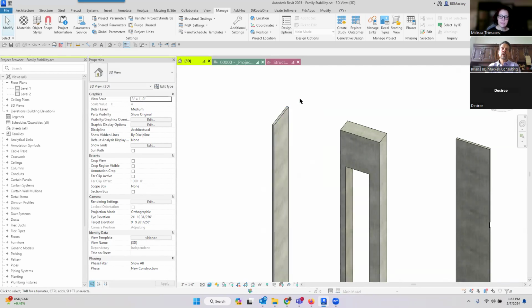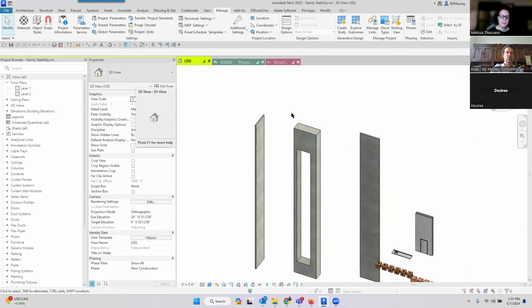So you can transfer, but again, you'd have to copy that one wall type out if you only wanted the one wall to a different project that doesn't have it. Blank file, and then transfer project standards over. But if you're talking walls and materials and all of it, it doesn't do it. And thank you to whoever typed in the JO tools. Yeah, they do have those, and I knew somebody had a tool, I just wasn't sure which one. There are tools out that say, I want to transfer, but I don't want to transfer this element and this element. So if you're really looking at doing it, it might be one of those things to look at too.